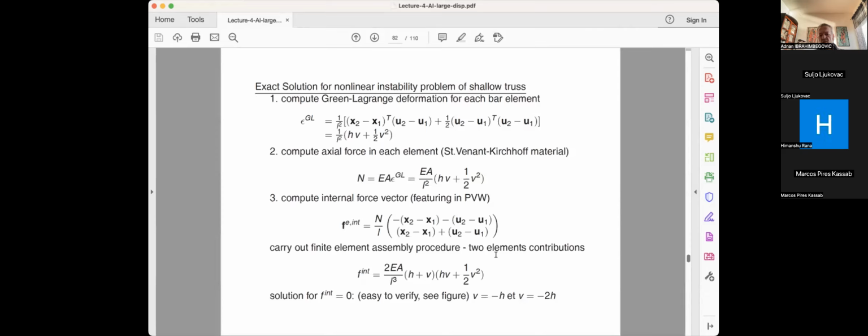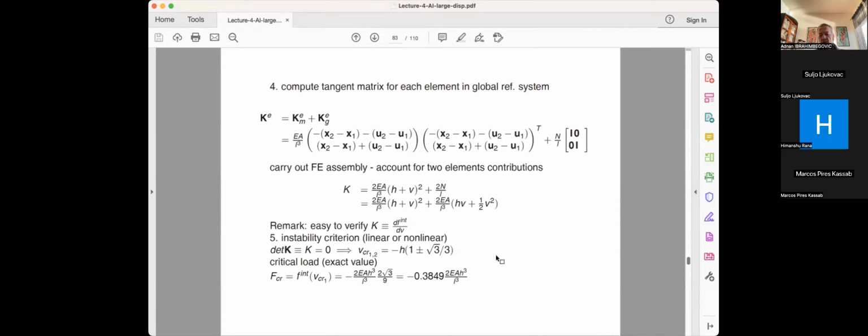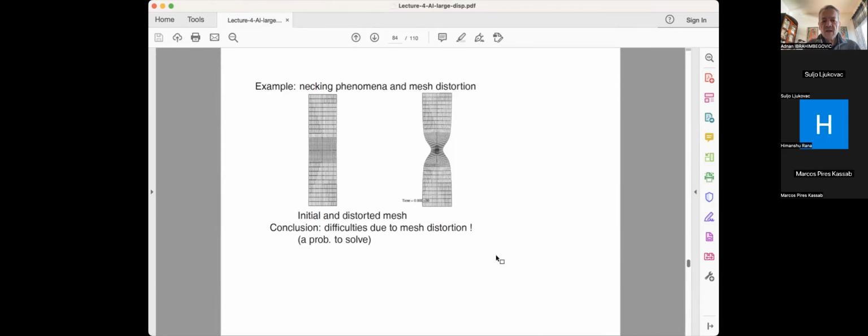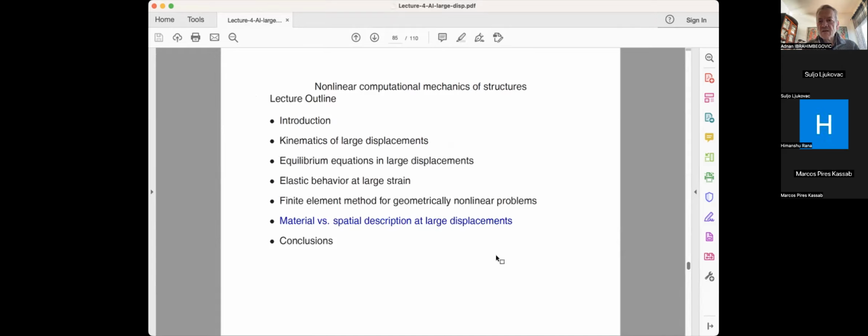And you can try to compute this with, let's say, linear instability analysis, and I assure you, you get a very wrong result, because typically this nonlinear instability is something which is very heavily influenced by the large pre-buckling displacement. You have this type of thing also when you go for plasticity, you have necking and stuff like that. So we study this as we go along. So I actually stop here, because tomorrow when I talk about constitutive modeling, it's good also to recall